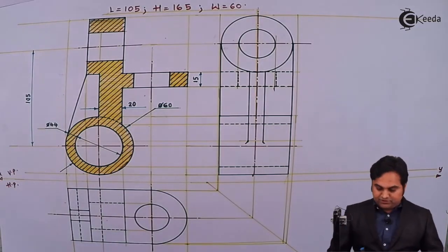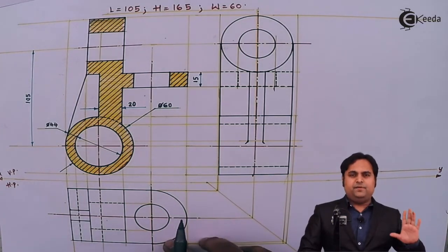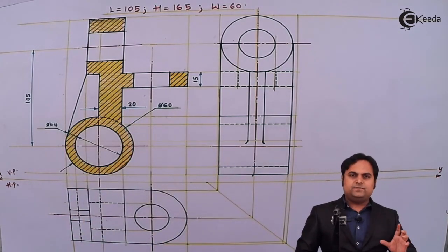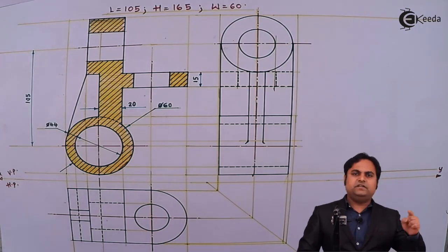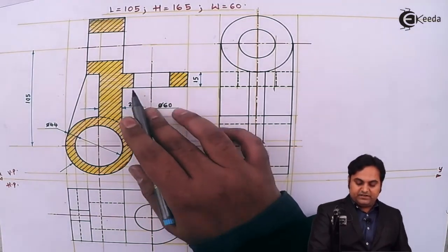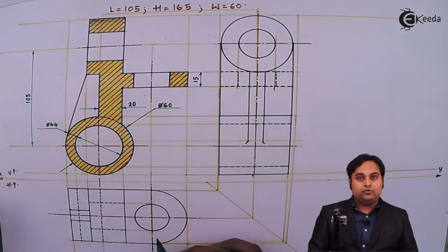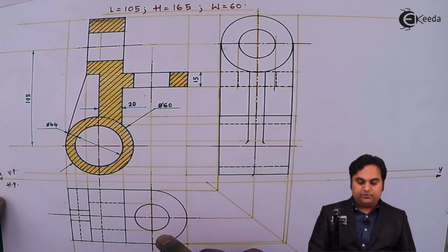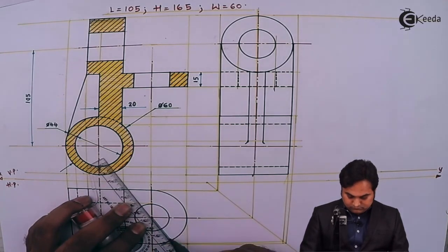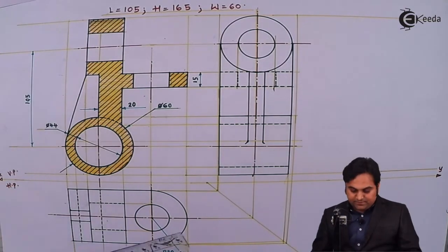And then after giving the dimensions in the front view, now I'll start giving the dimensions in the top view. And remember, whenever you have circle or semicircle where you are getting their true shapes, that is their exact shapes, then give the dimensions there. Like for example, if I look at this plate in the front, this plate is looking like a rectangle to me, but when I look from the top, that plate is actually a semicircular portion. So I'll have to give the dimensions here because here I'm getting the true shape. Radius 30 mm.